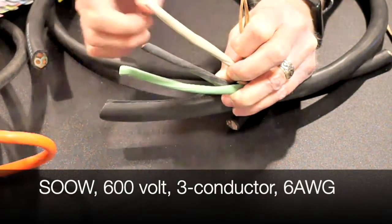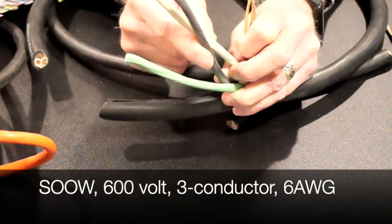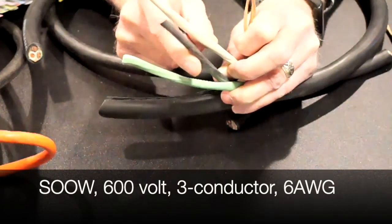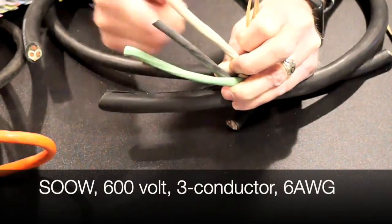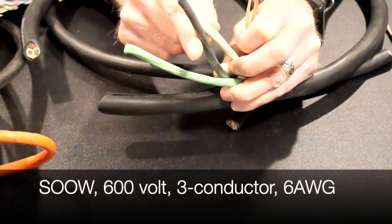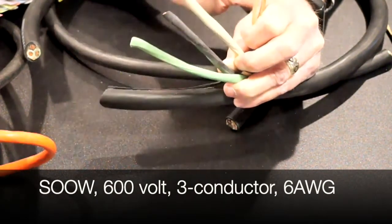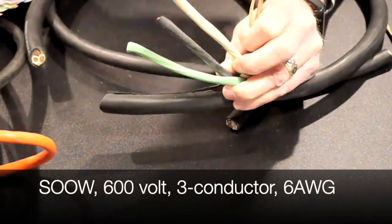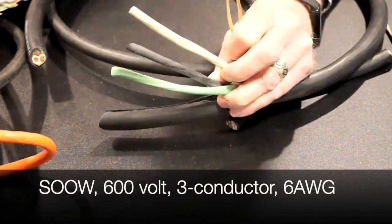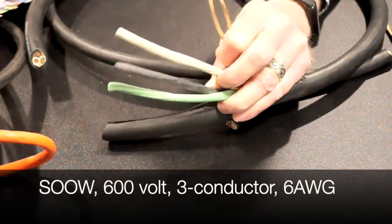Now, when it comes to calculating my ampacity values, what you have to remember is you've only got 2 conductors that are current carrying, right? So that's going to place you into the proper column on the table for ampacity values. So you've got to remember that, how many are current carrying and how many are total conductors inside of the flexible cable. Now, if we were to go to table 400.4, if you remember, it's the one that provided us all the information on the different types of cables.